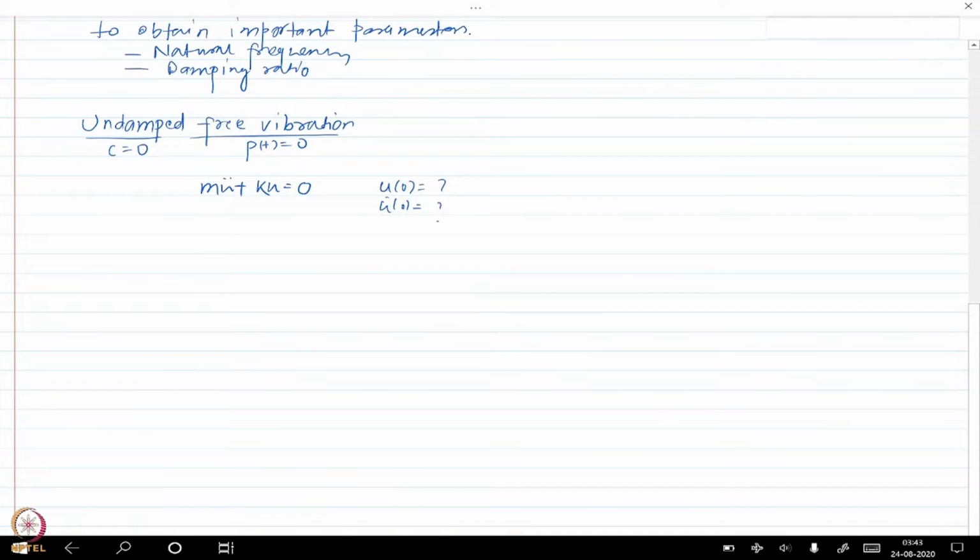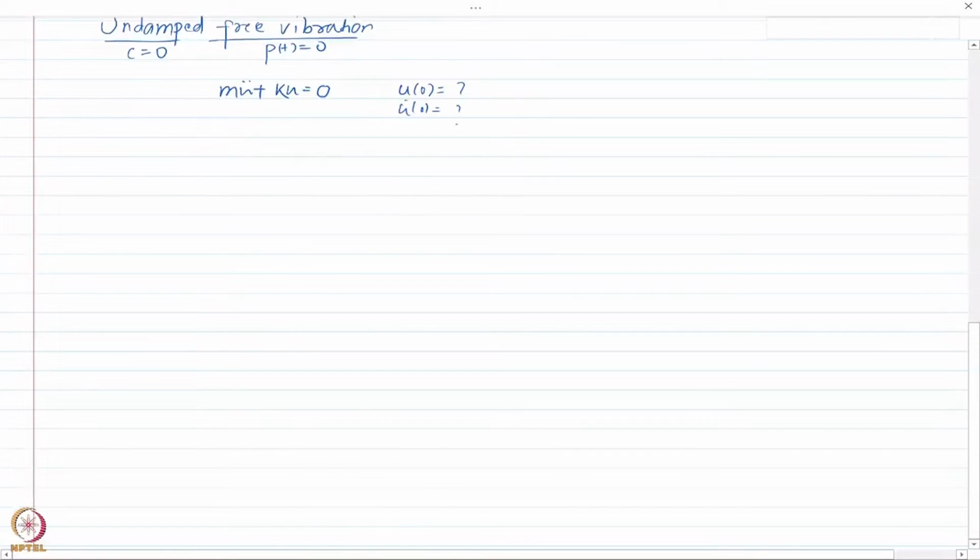All right, so what we are going to do, first we are going to solve this system and obtain the analytical solution for u(t). Okay, and then we are going to get into the physical interpretation of the response for the free vibration. So, solution to a second order linear homogeneous differential equation. Remember that we now don't have any term on the right hand side of this equality. So we discussed how to get the solution of a homogeneous differential equation.